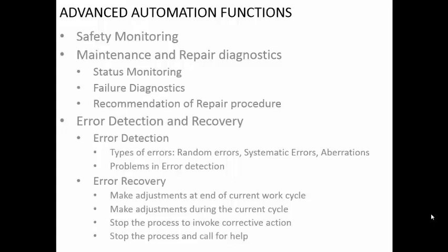When the power has again been received, from wherever the program has stopped, from there itself the program has to restart, which means usually when the power is switched off, the tool will be moved away from the workpiece. When the power has come back, again the movement has to happen. So this kind of error recovery has to be implemented into the system. So whenever power is going off, the tool will not start from the same position. First it is to go back and then it will come back nearer to the workpiece, and then the machining process will be continued.